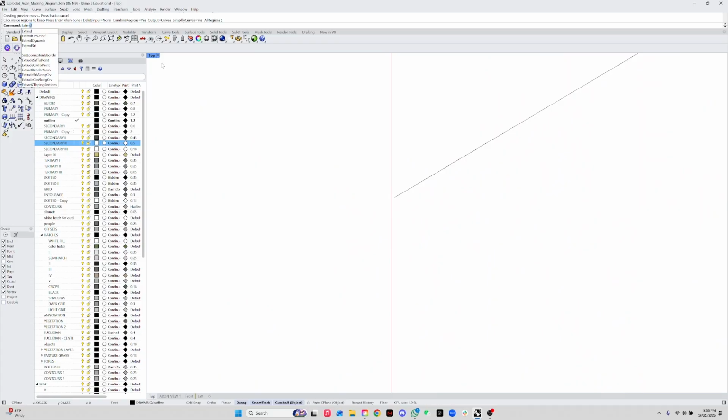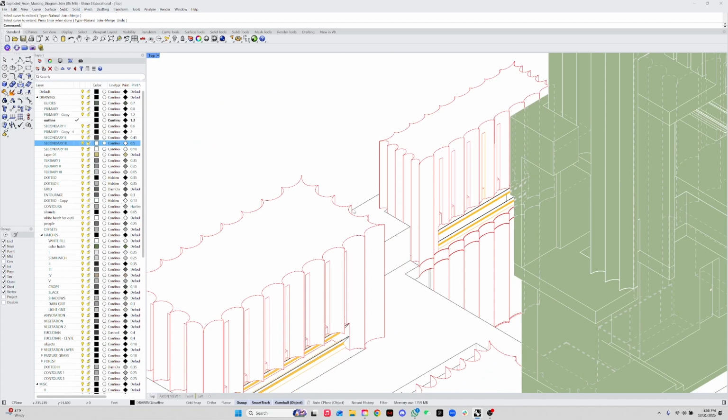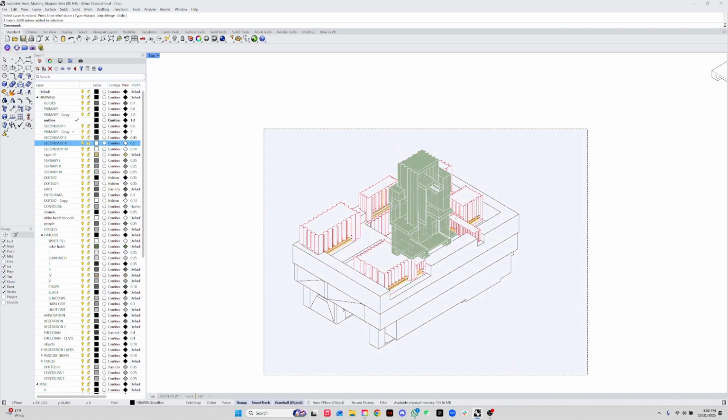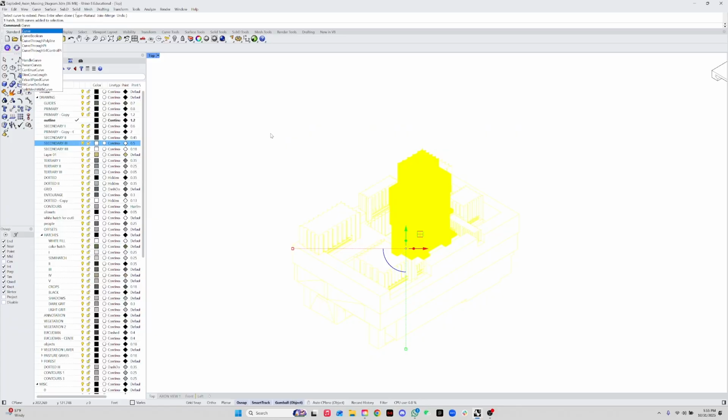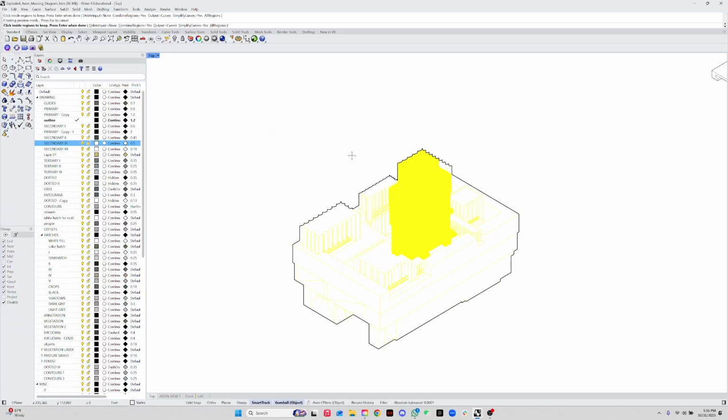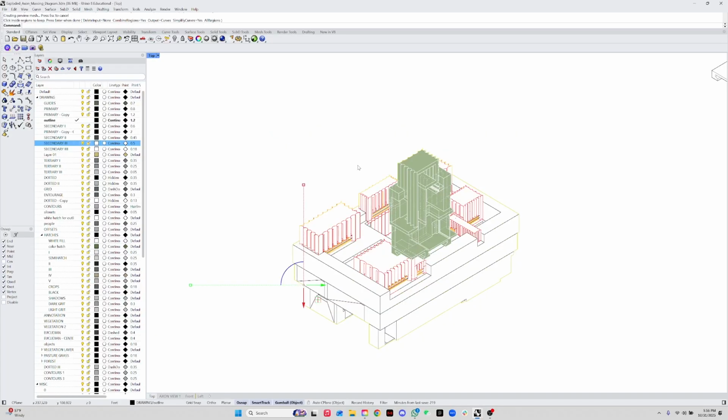I'm gonna extend that. I'm gonna use the command extend. I'm gonna click this line, click the other one, press enter. So click, and then this line extends, or you can do it manually by clicking the point. So now it should be okay. I should be able to select this whole thing, curve Boolean, then click outside, and then I have my line.